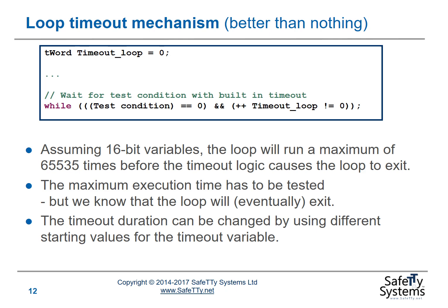This is not precise. It has to be rechecked for each system. The time delays will vary with compiler optimization settings, etc. But this kind of timeout loop mechanism is better than having no timeout mechanism at all.